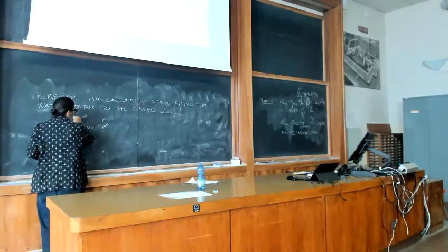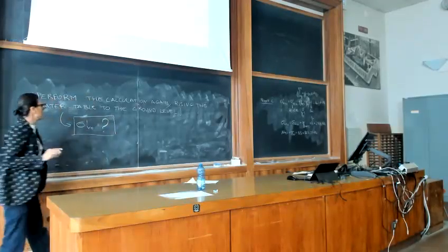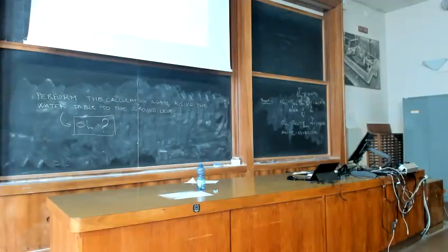Try to make a comment about the comparison between the diagram of effective vertical stress state in this condition and the new one. And then tomorrow we can start just doing a very short comment about that and discuss practical application. This is very important. The only variation for the second part of this application is rising water table.